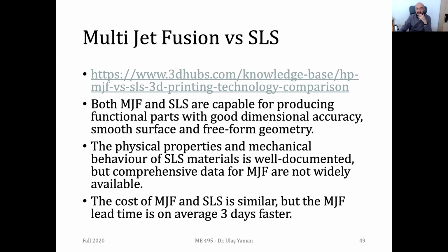So in summary, they are producing very functional parts, assemblies. Their accuracies are quite good. They have a kind of grainy surface, but it's fine, it's acceptable. And their mechanical properties are quite the same. And the thing is that MJF is quite better in terms of, let's say, lead time or cost, since you can recycle many of the powders.